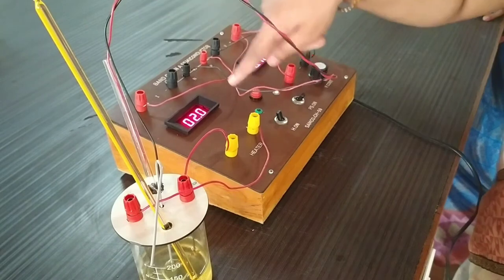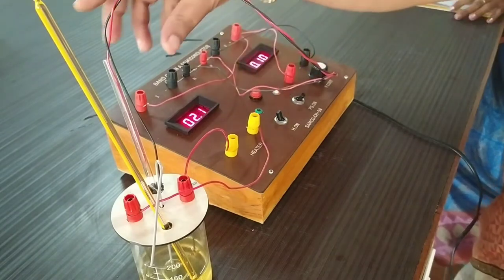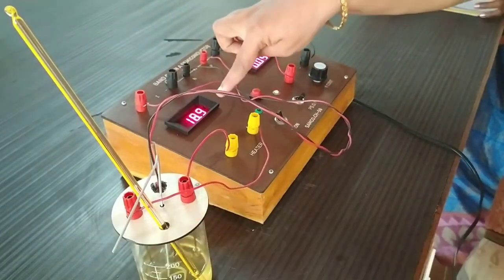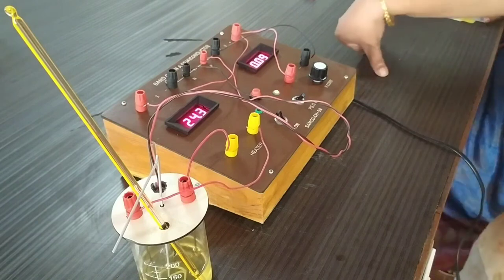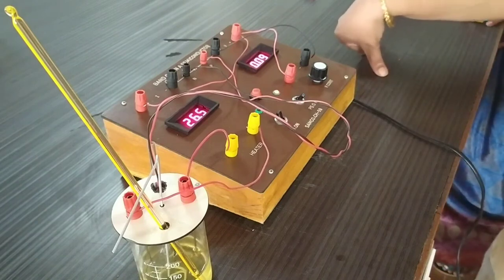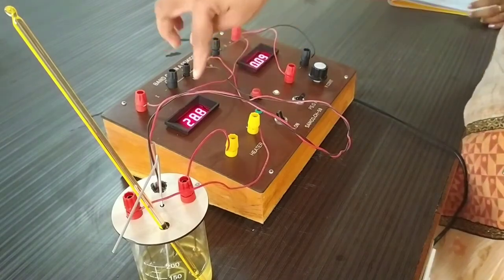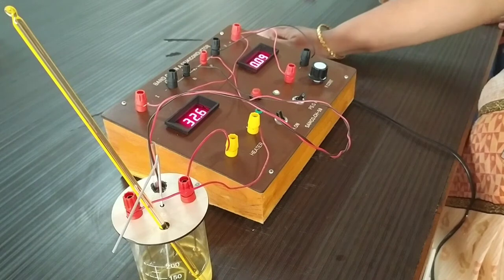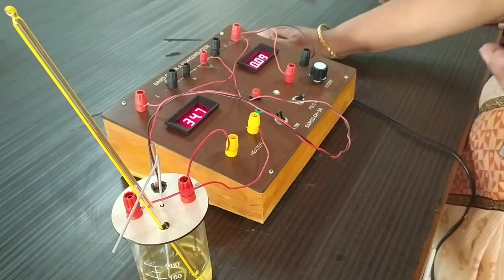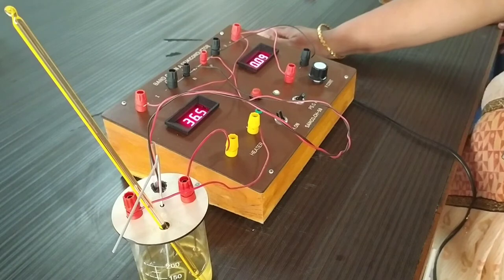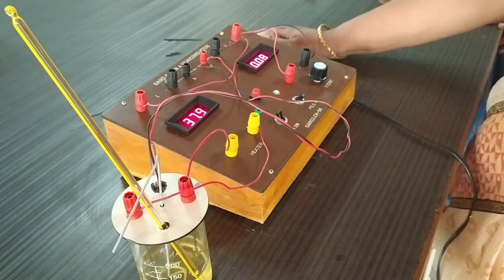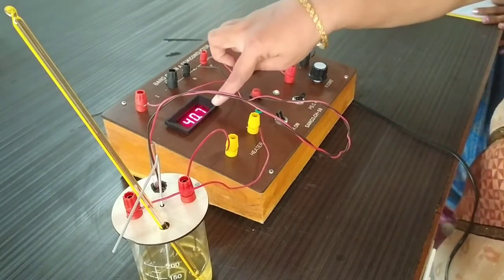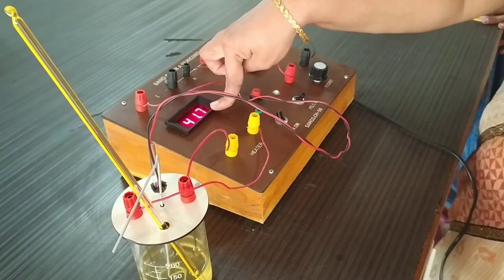See now, the reading is some 2.0, isn't it? As I introduce this diode inside the hot temperature bath, you can see the reading drastically changes. Yes, can you note down? Now we can say that because of the temperature given, the electrons from the valence band are getting raised to the conduction band, crossing the energy barrier. How much it crosses, we are going to measure using reverse saturation current. For that only we are going to measure this amount of current here.